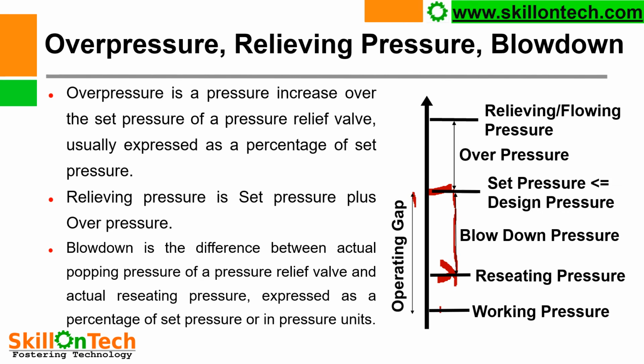This is your working pressure. So generally the set pressure is more than 10% of working pressure. And this is the relieving flowing pressure. Your valve will pop up at set pressure.